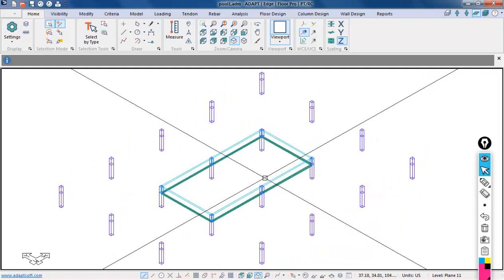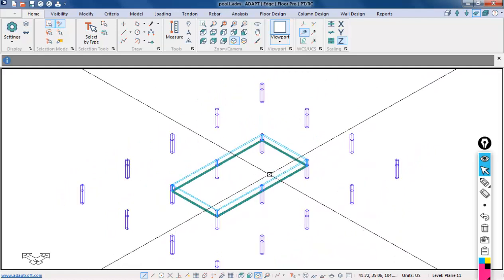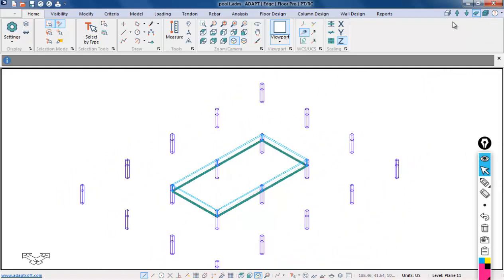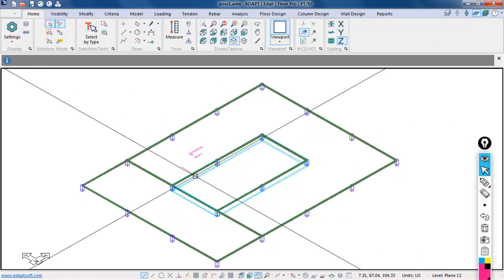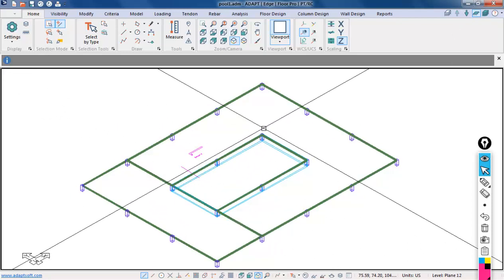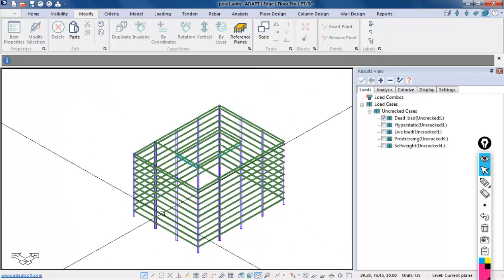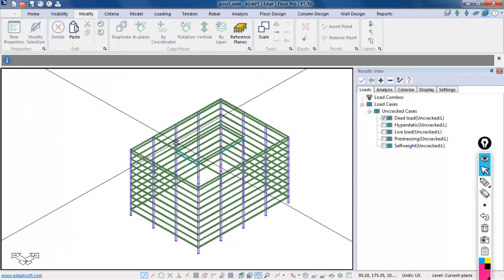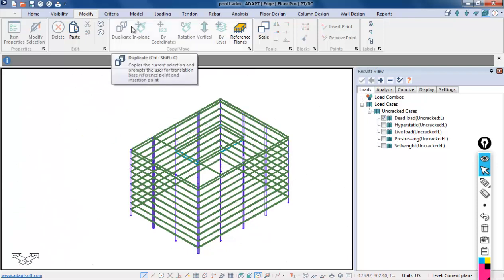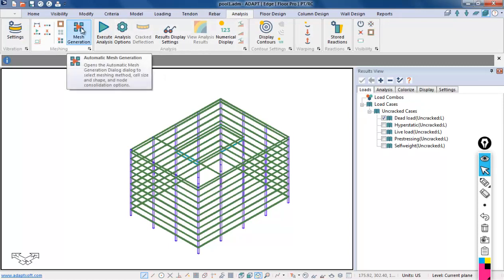This requires the model to be performed in global mode, because if I perform this in single level mode, there's no slab at the bottom of these walls. Those walls just get supported, and this becomes essentially an opening. We will now just mesh the entire structure, because we're going to run the model globally in multi-level mode. So I'll go back to analysis, and I'll mesh this.